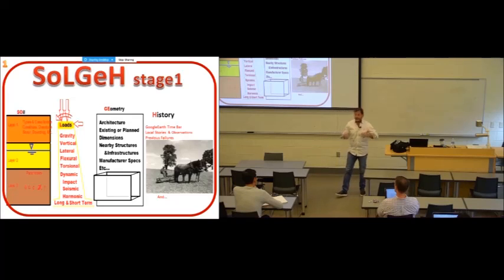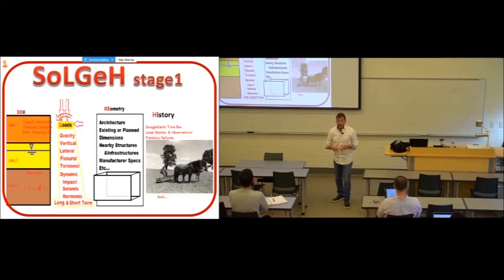formulate the problem. So collect the soil, what are the parameters, where is the water table, any history in that area with failures or any problems with the neighbors, have cracks, etc. The loads, what are the loads involved? In our case today, we're going to concentrate on laterally loaded structures.